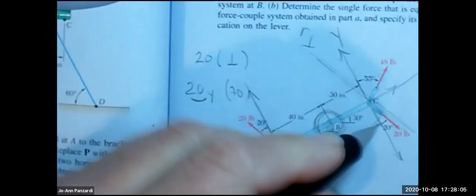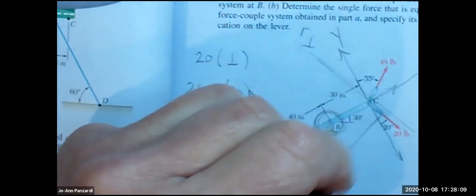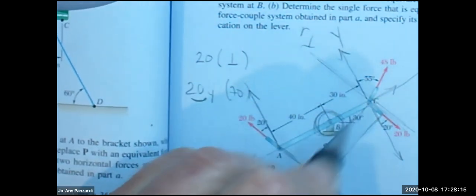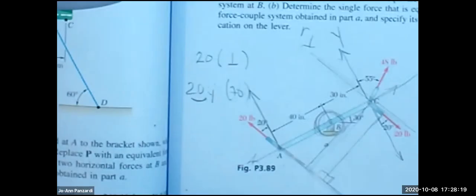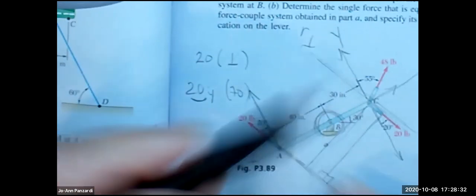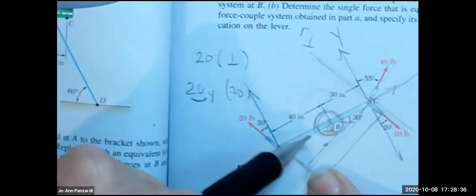I don't quite follow that. I think the distance between A and C is still 70. So if you had them off at angles like that, it would still be 70, right? No, you can't, David, because the rule with couples is you multiply the couple force by the perpendicular distance. And the perpendicular distance is this distance right here, this leg of that drawing triangle. I got it. That drawing helped. Thank you. Okay, great. Everybody see that? So if you're using the Y component, then you could use the 70. Gotcha. It's the same math though, right? If this right here is 30 degrees, let's see, that's not 30.